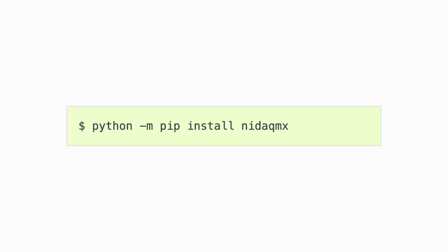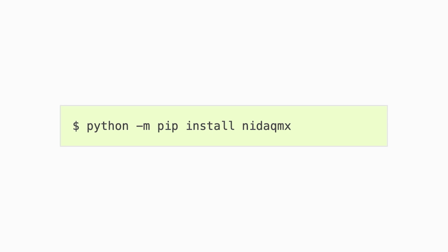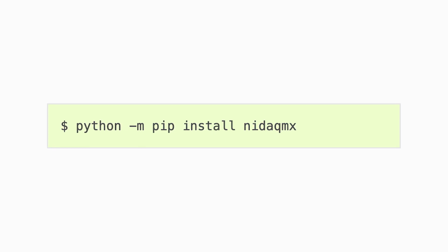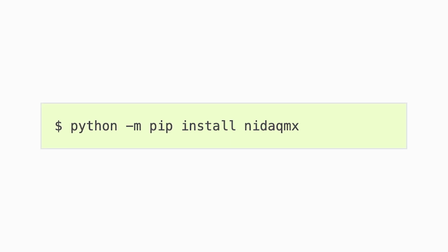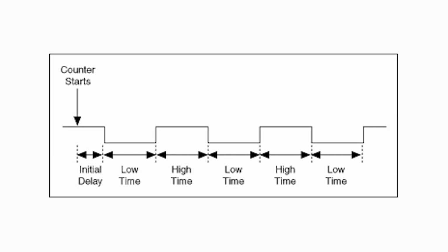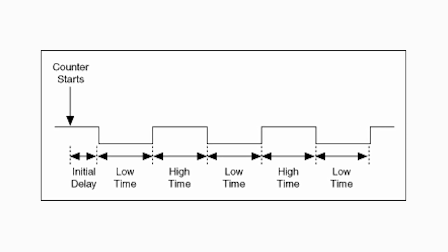Now in Python, we begin by importing the NI-DAQmx Python library, along with the acquisition type class, which helps define how our task will behave. If you haven't installed the NI-DAQmx API yet, pause here and run the following command in your terminal. pip install nidaqmx.